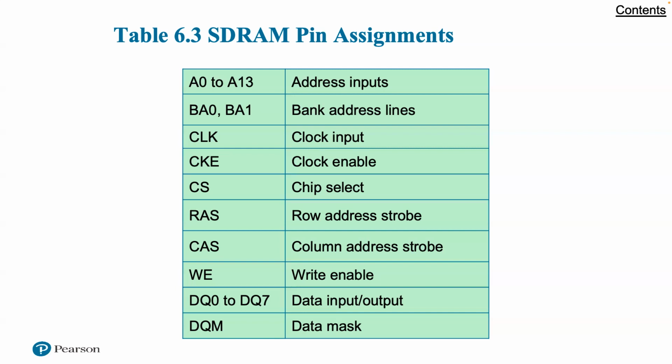The mode register and associated control logic is another key feature differentiating SDRAM from conventional DRAM. It provides a mechanism to customize the SDRAM to suit specific system needs. The mode register specifies the burst length, which is the number of separate units of data synchronously fed onto the bus.